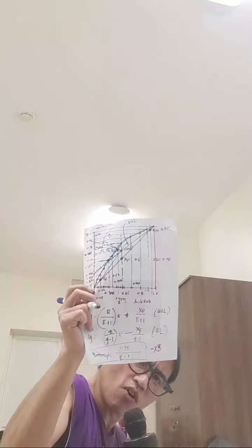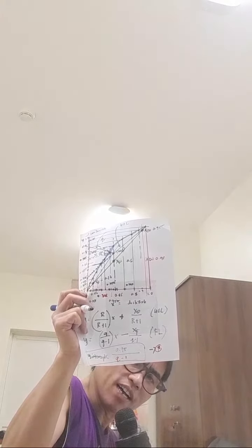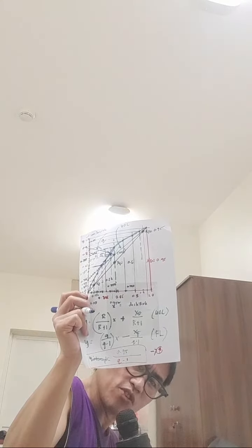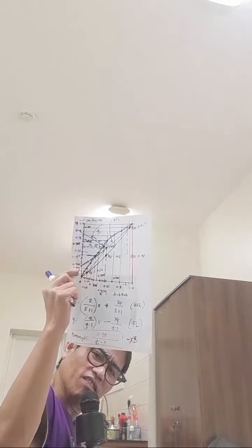Remember this, guys, the y-intercept's purpose is only to create the feed line. So after counting the trays of the distillation unit, it will never be needed. So cancel that one, and what will be left is this one, the line at the bottom. And then we create the trays.